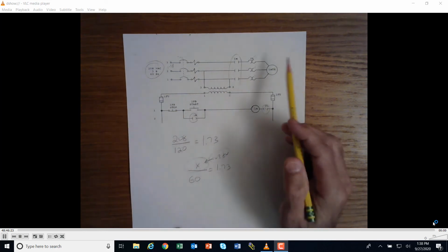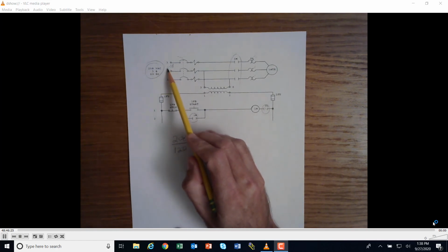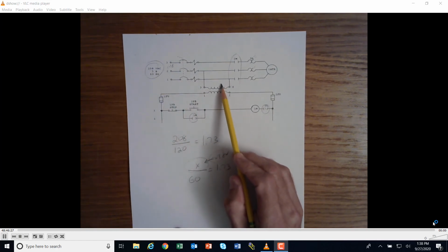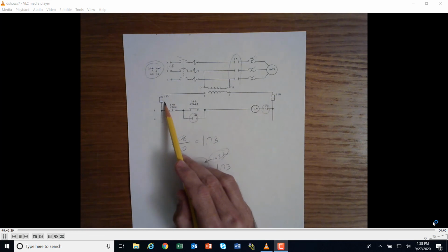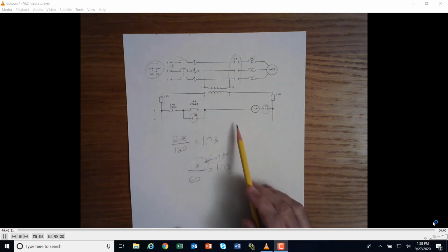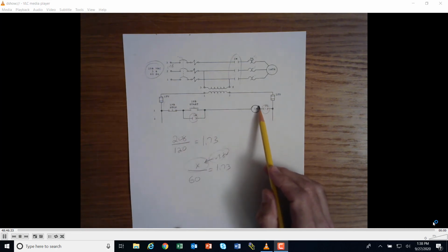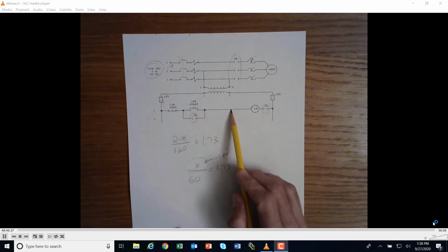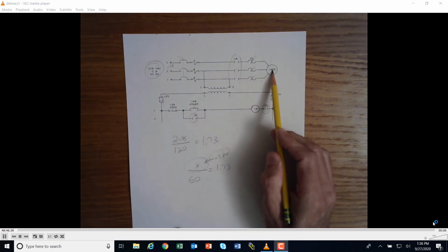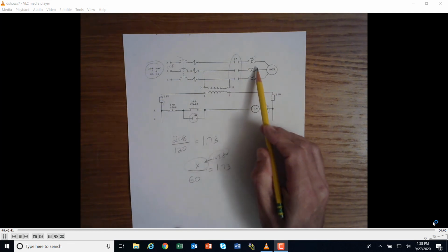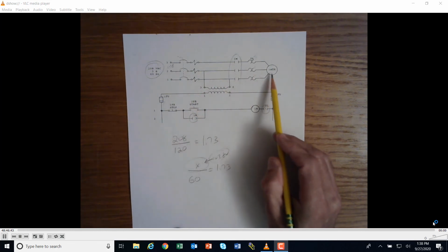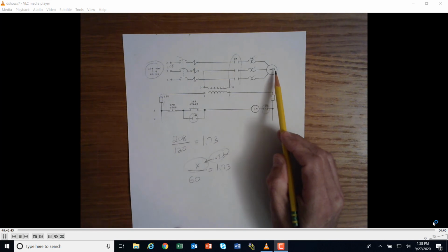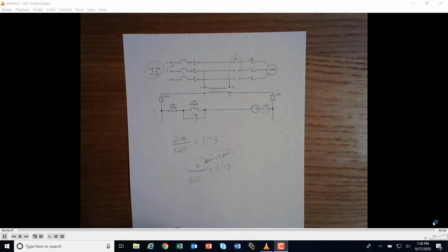So when you get a low voltage situation here, when this starts dropping, because the transformer has a ratio here, the voltage between line and neutral starts dropping as well, and you hope that somehow this control circuit drops out before the motor burns up, because ultimately line 1, line 2, and line 3 are getting some pretty low voltage, and that could cause that motor to get damaged.